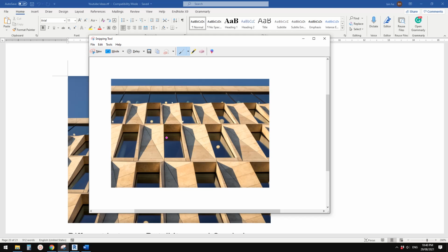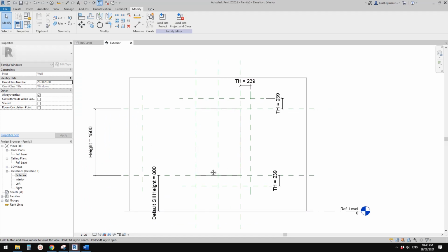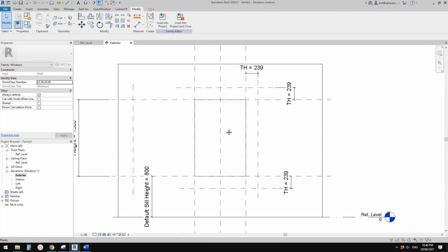So what I'm going to do is I'll just create a solid. Okay, so a solid extrusion, and then we're going to cut away part of it, so see here, cut away this, and then cut. So use void to cut all these edges, all the frames. So let's go to elevation. First we need to create a solid.